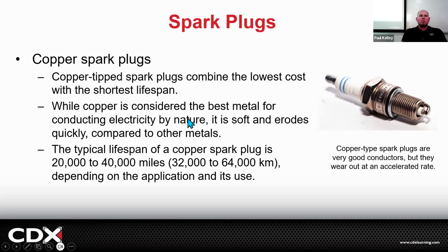That copper, yeah, copper would be like a lawnmower. That'd be like a Champion, you know, right? That's a cheaper, more basic spark plug in an older car. It's fine if that's what the car ran originally. Champions were good, but more what I mean was Champion was a plug from back in the day. Champions aren't coming on any new cars. Yeah, so that's more what I mean. If you got a car that's got a distributor, cap, rotor, and plugs, I'd run all the original stuff on that.